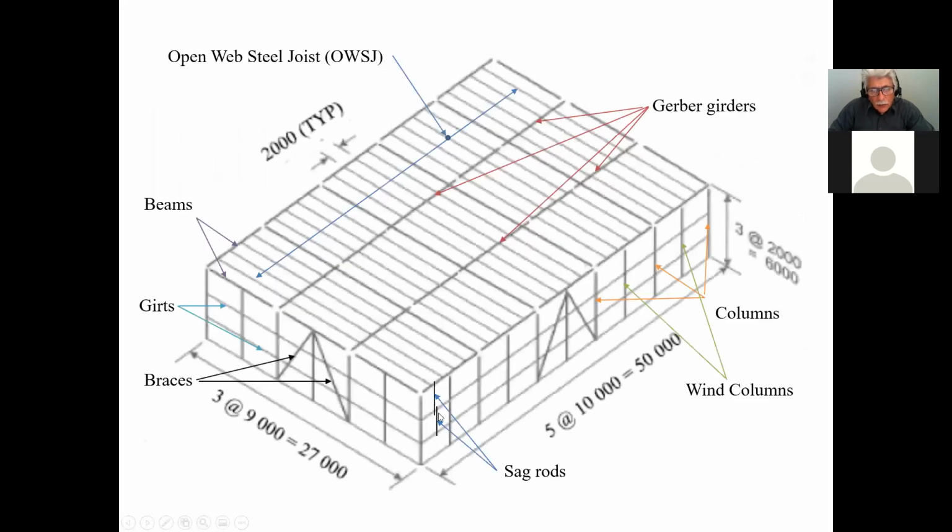Okay, so that's what these things are. Now, because these things are supporting a dead load onto this beam, you should make an allowance for a dead load, because what is a dead load? A dead load is the self-weight of the member plus any permanent construction that is going to be supported by it. And of course, these things are fairly permanent. Therefore, these two members here will contribute to the dead load.